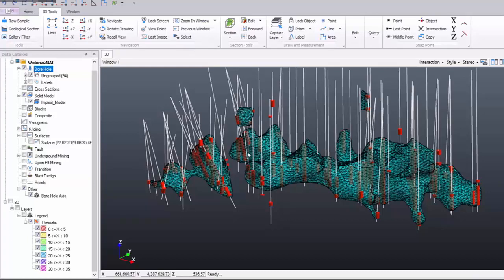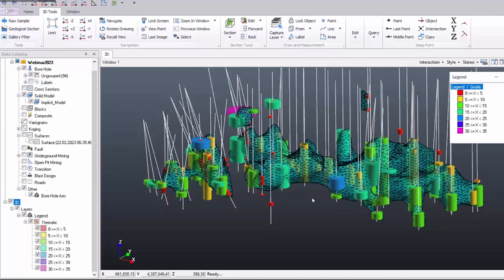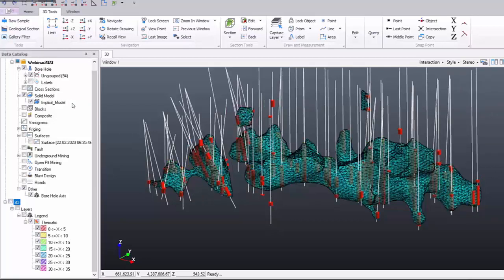The last thing that I have to do is making an estimation. Once I'm able to assign the grade values we have in the boreholes, I will make an estimation. With that, I will be able to estimate how much volume of material I have in terms of grade. So this is my model, and basically if I check its properties, now all that I can learn is volume information. Let's check.